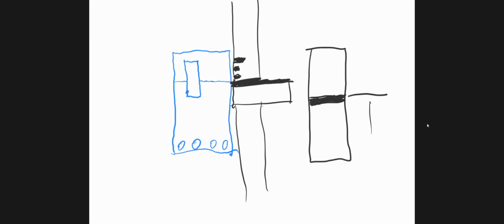That's where you take your reading, at the top of that bar when you see it in the window, which corresponds to this line that is projected across. Same thing if you're too high, you'll see arrows pointing down, and you'll hear a slower beep, beep, beep. So you can tell by the beep if you're too high or too low, or you can tell by the arrows.